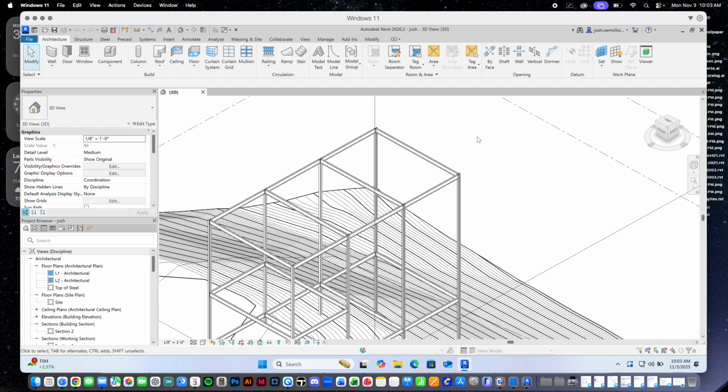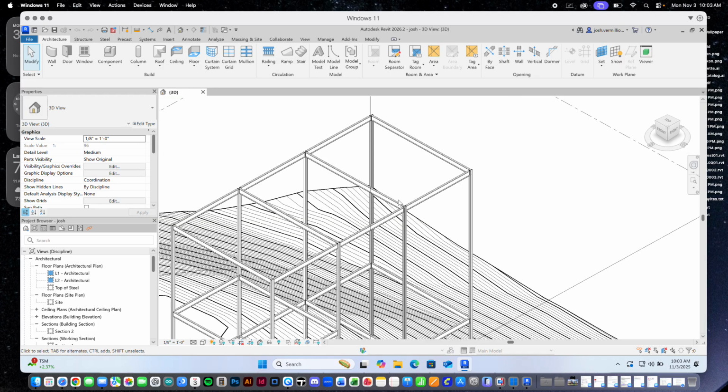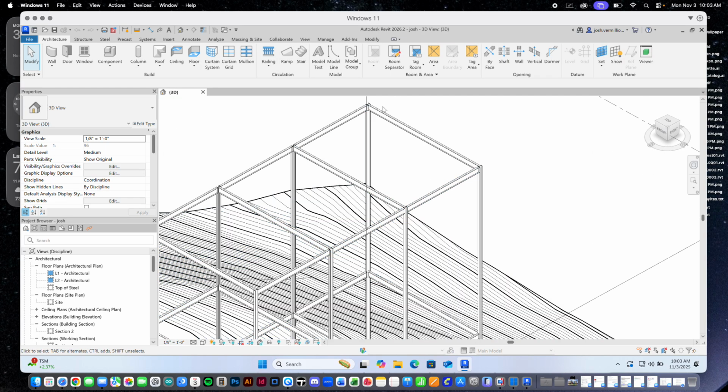All right. And this is going to be a sort of refresher anyway of what we were doing, drawing beams. We'll draw more beams. So if we think about this, we have our structural grid. These larger beams, we're going to have smaller beams that span in between and frame into them. These bigger beams, we typically call girders. And now we'll start to draw the joist beams that actually frame into them.